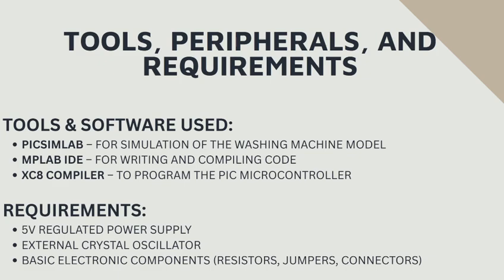microcontroller. As for the requirements, we needed a 5-volt regulated power supply for the microcontroller, an external crystal oscillator to maintain accurate timing, and basic components like resistors, jumpers, and connectors. These are very essential when building any embedded system.